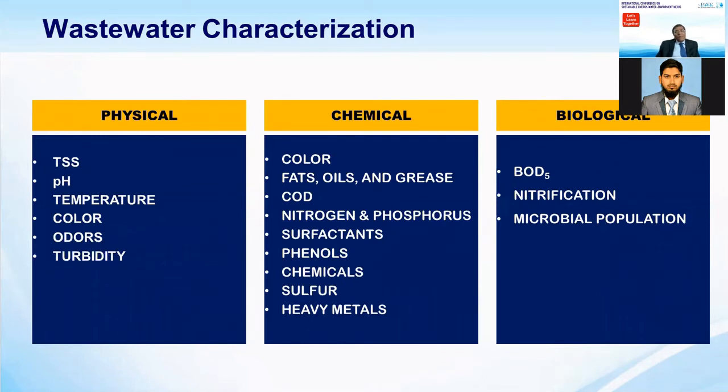In DHA, at one PSO station, we installed a CPI separator 10 years back for removal of oil from the wastewater coming after washing of cars. If somebody wants to visit, they can visit the PSO petrol pump in DHA Karachi. I don't remember the name, but maybe Kamran will know it and can guide you. Through these plate-type CPI separators, we are separating the oil.